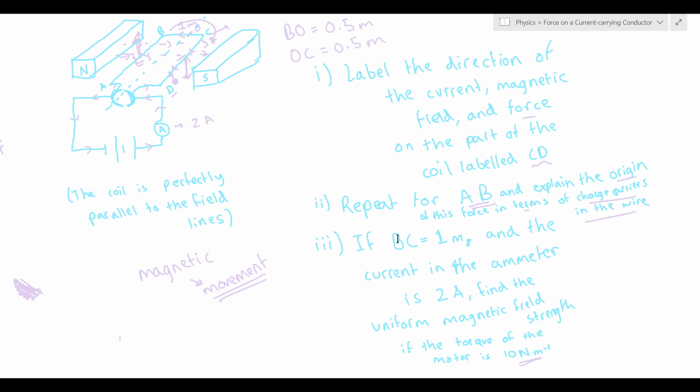So this 10 newton meter torque is going to be equal to the torque of this arm, which is, let's say F, the force that is being exerted, times the distance from the pivot, so times 0.5, plus for this arm again we have F times the distance of CD from the axis, which is 0.5 meters, which is equal to just F, the force. Also, sorry, this should be newton meters, because torque is going to be force times distance, so newton times meters.